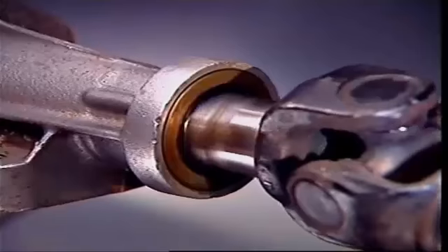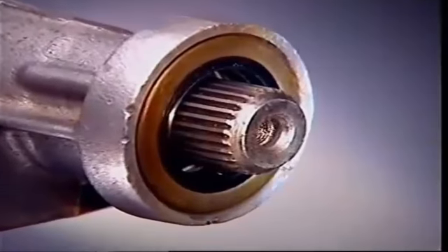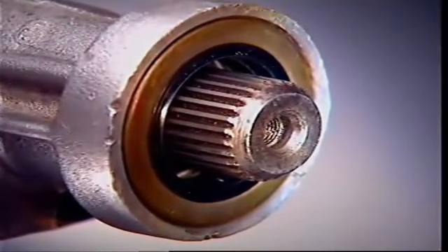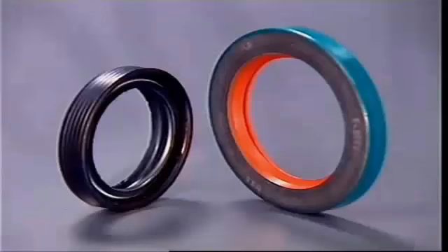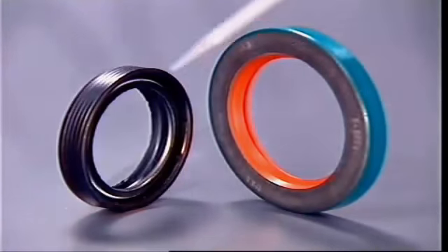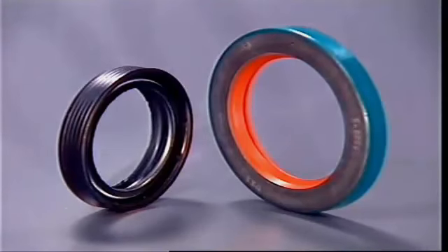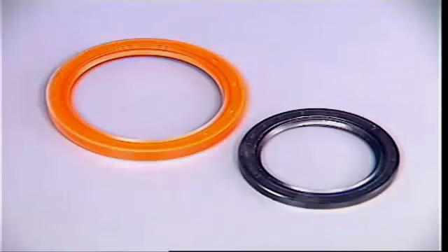Where the shafts extend from the casing, oil seals prevent oil leakage and the ingress of dirt and moisture. Garter spring lip type seals are normally used. They can be single or double lipped, depending on the application. They can also be hydrodynamic type seals, with helical flutes moulded into the sealing lip.